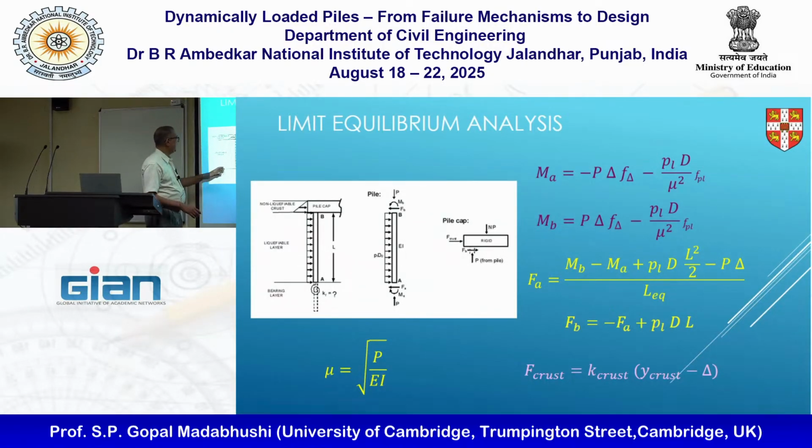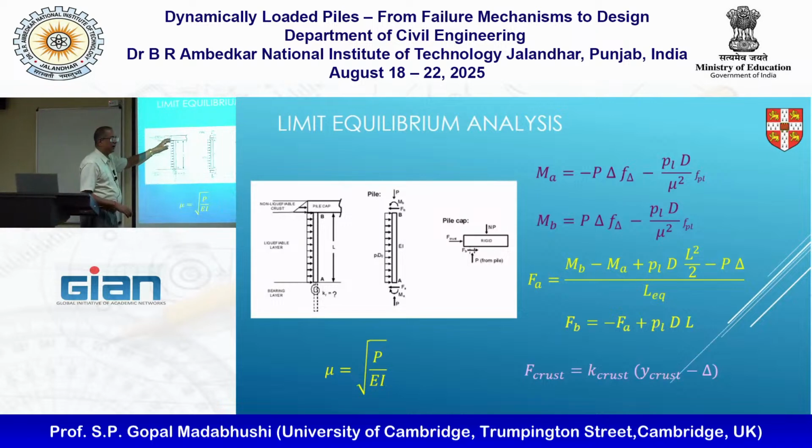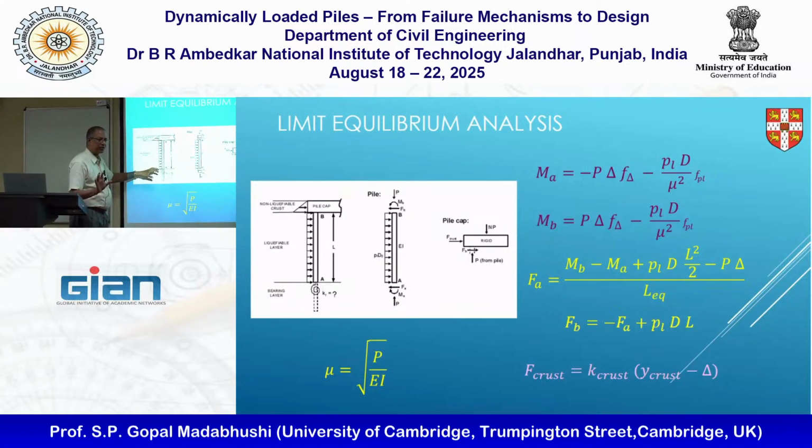So, say you are in level ground to start with, you can say the non-liquefiable crust is going to apply the full passive pressure. So, for clayey soils, you know how to work out Kp. You should have done that in maybe a third year geotech or fourth year undergraduate course.